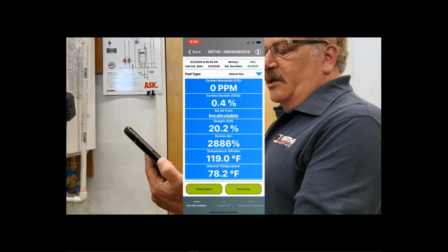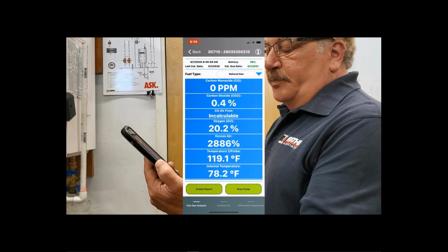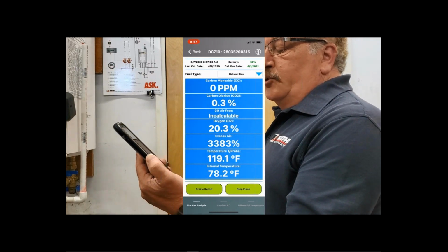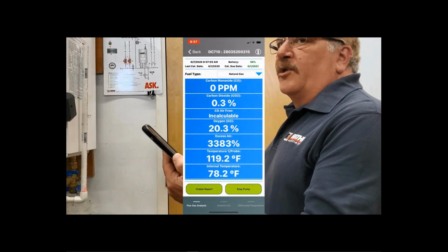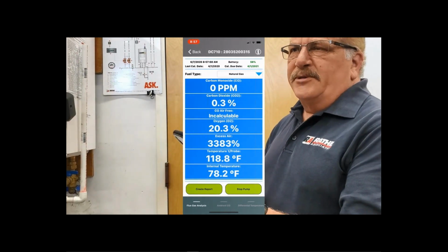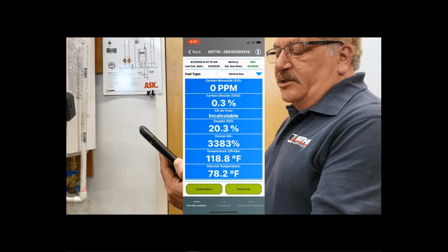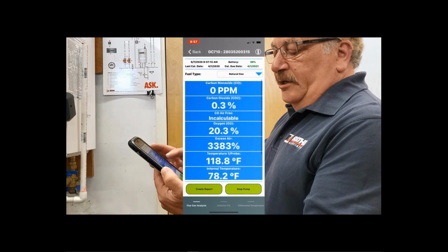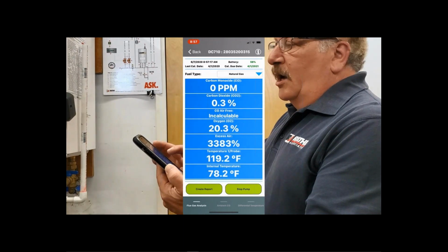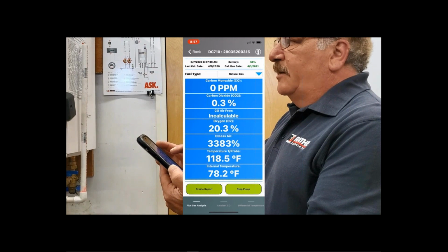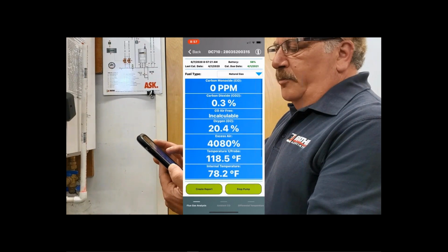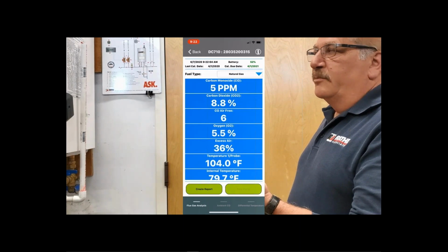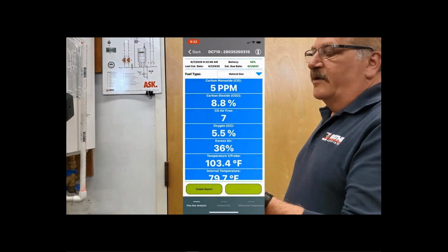They do take time to take those samples through the pump and display them on your applications. Underneath that, you're seeing 20.2 oxygen level. We start with a 20% oxygen level normally, and we're seeing excess air and temperature readings. So at this point, we're going to allow our device to take those samples, and we'll be looking at those in just a moment.